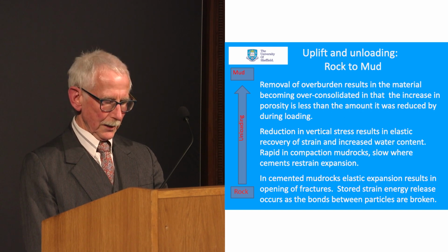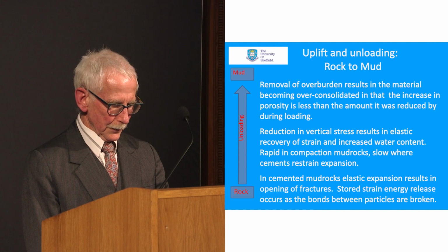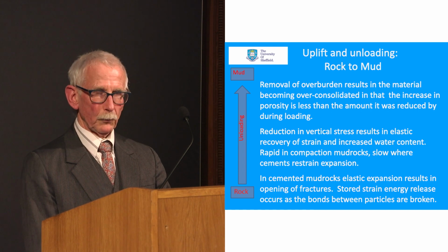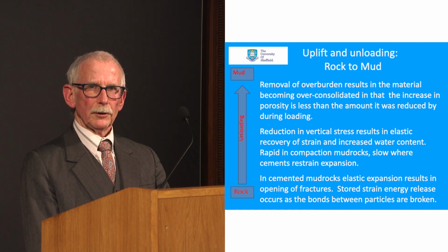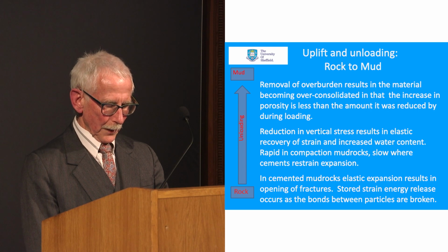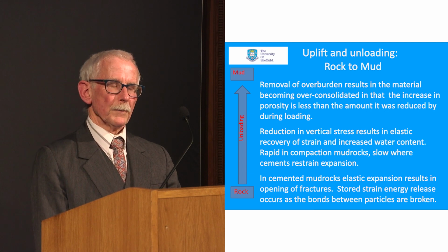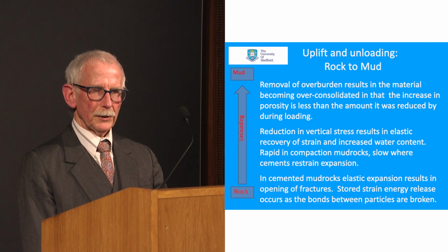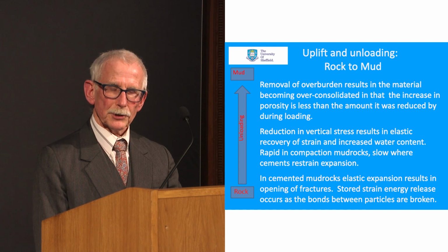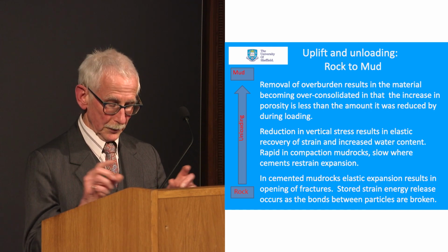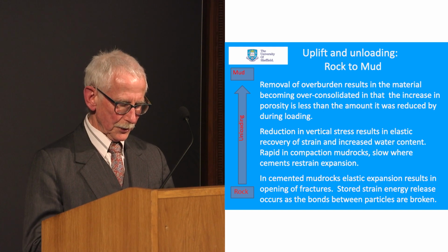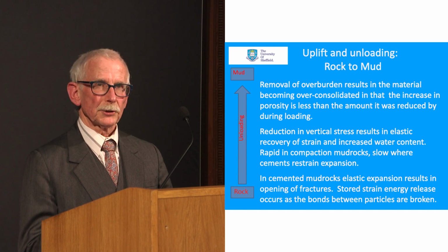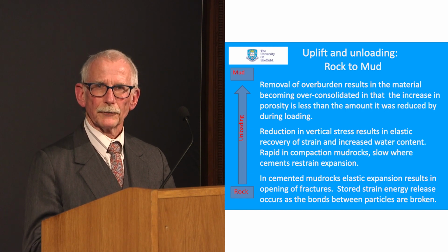Mud rocks are prone to slaking, and by this I mean that when wetted, the water traps air in narrow capillaries within the rock, and as it's dried, the removal of the water forces the air into narrower and narrower pores, such that the air pressure, because of the surface tension effects of the water, increases in the narrow pores, and this can increase the pressure to the extent that it can exceed the tensile strength of the rock and cause it to be broken.